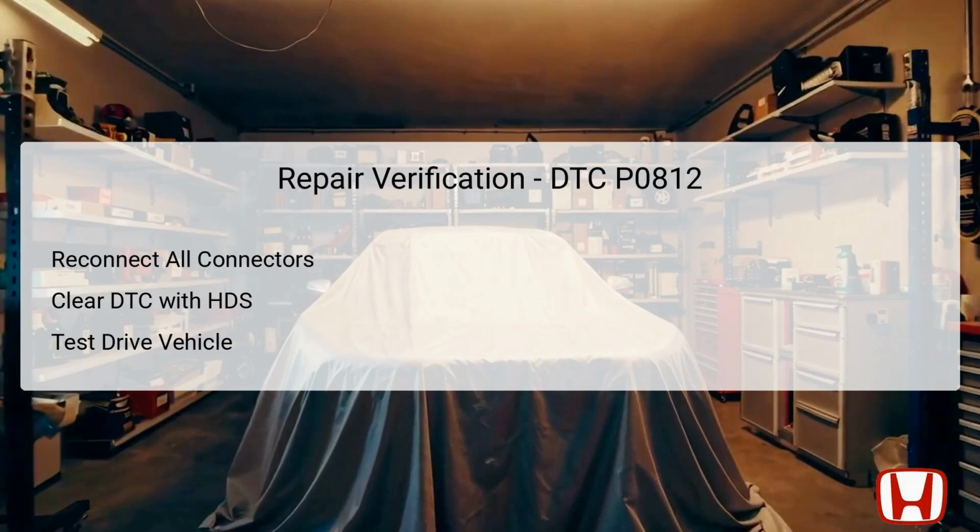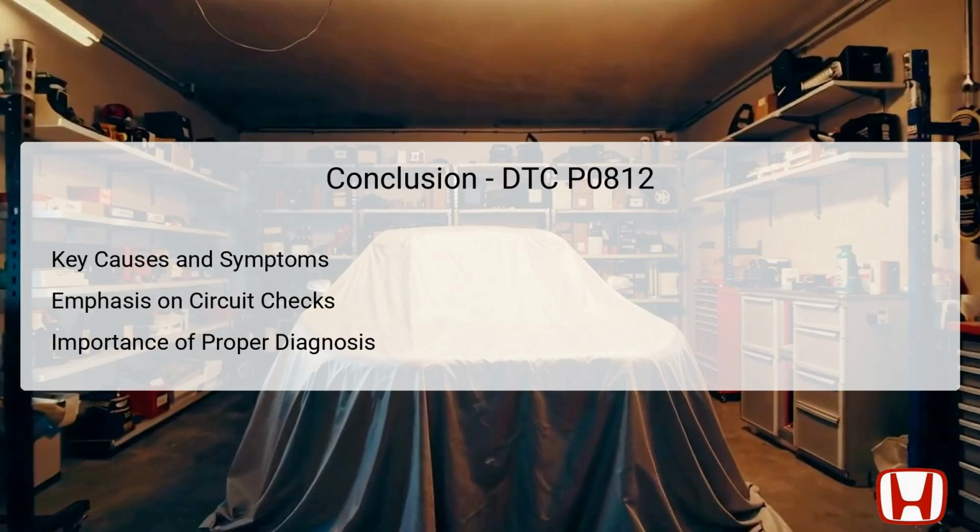In summary, DTC P0812 emphasizes the importance of a robust approach to diagnosing potential electrical issues within the transmission range switch circuit. Primary causes include electrical circuit problems and intermittent faults, underscoring how critical thorough circuit checks are when diagnosing this DTC.